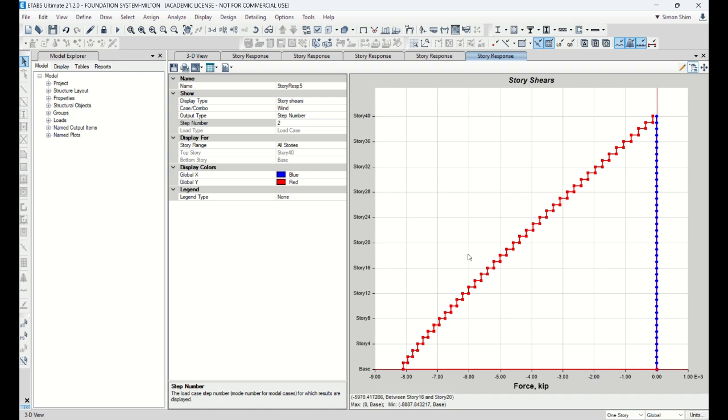What you need to do is you need to define, create this wall section property and concrete strengths, various concrete strengths, and then in each group you can just assign the wall and link beam in a similar way and do some iteration. I think your building, your core wall is much deeper, 50 feet, for a 40-story building. Yeah, obviously you don't have much slenderness effect. So based upon current analysis, the wall thickness 12 inches seems okay, but that's not a realistic size of the core wall. Okay, I'm gonna stop here.